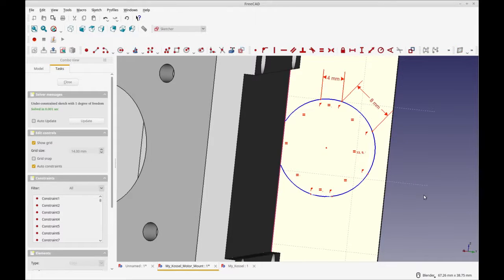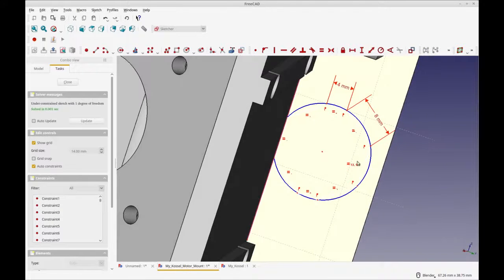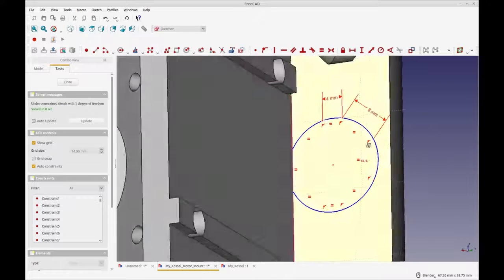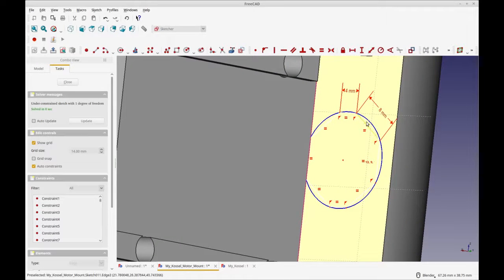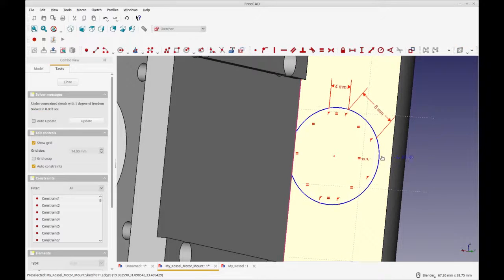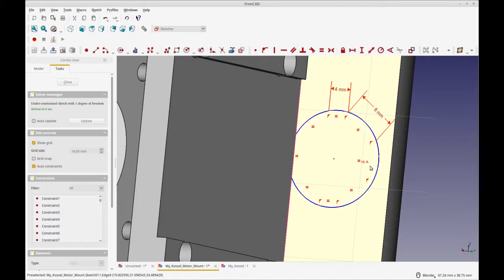Constrain it. So now it's oriented the correct way we want it, and we just need to give it a radius. Oh, I'm sorry, we don't need to give it a radius. We gave it an effective radius because this is a circumscribed octagon here. So you can't change the size of it. You can change the position, and that's all.